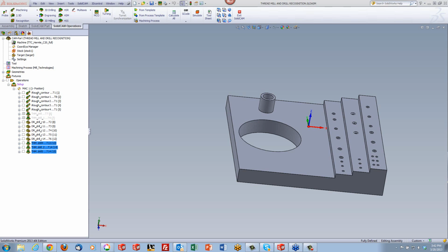There's one more question I see. As far as the last question, does a thread milling operation use a drilling cycle? True, and it doesn't show the tool movements. In the drilling cycle, you do not see the movements over there. That is true, because it in itself is a drilling operation. So it'll just go up and down as far as the simulation goes.